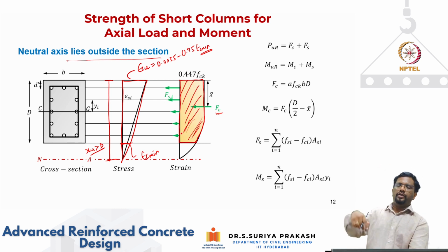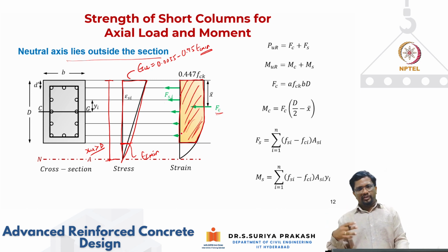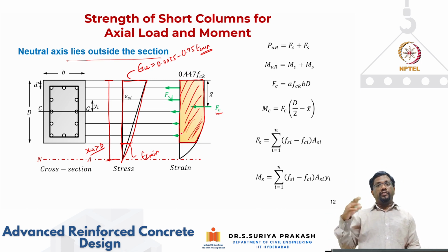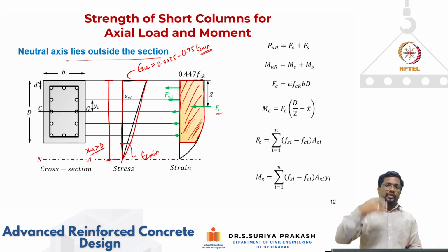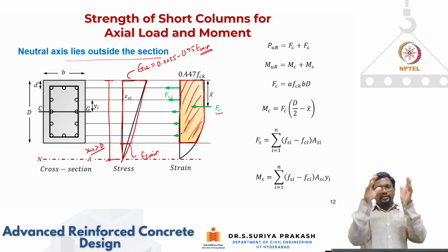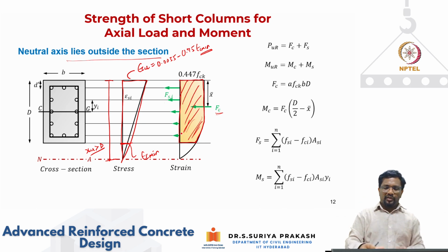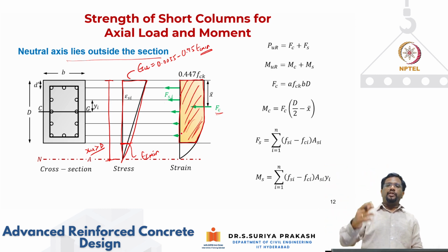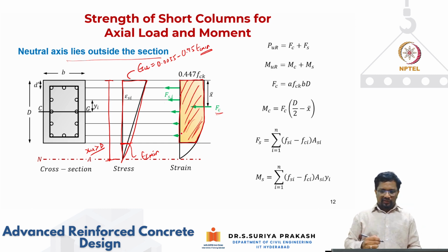Okay. For a parabolic model, what we have discussed in moment curvature analysis, we converted them into an equivalent rectangular stress block. So we can quickly calculate because everything is converted into an equivalent rectangular block. But in this case, for the IS code, you have a parabolic portion and then a straight portion. So deriving that alpha and beta is more involved. Okay, so this aspect you have to keep in consideration.